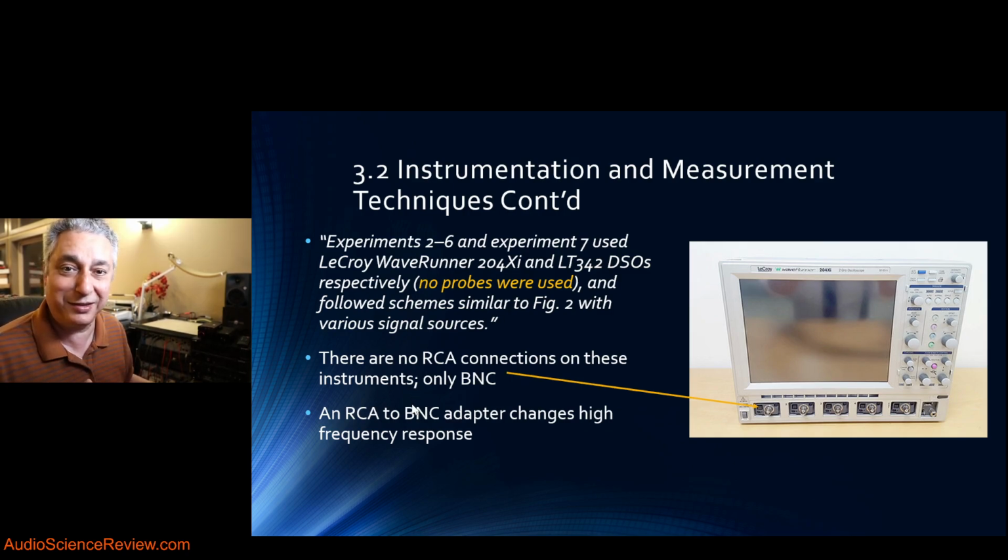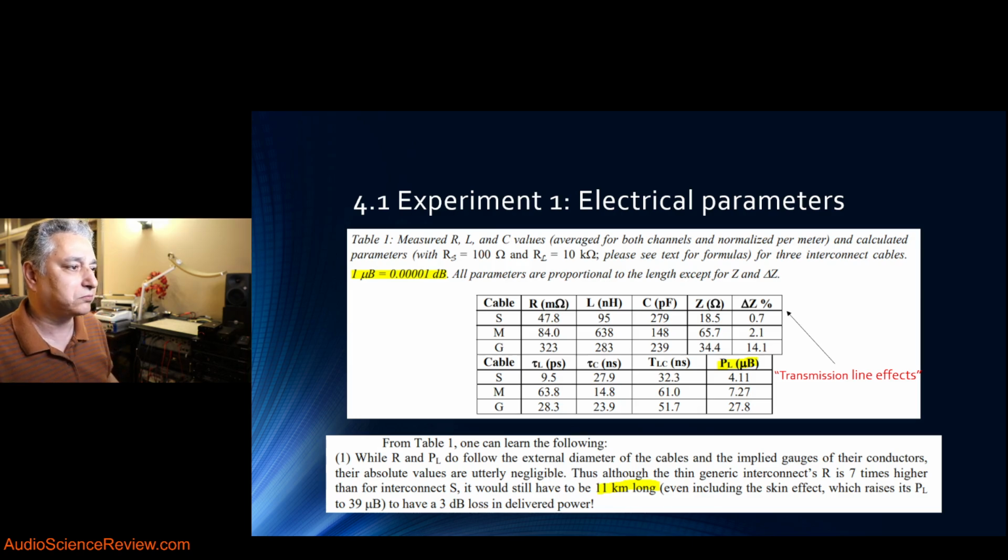The cable could be quite innocent. And so these are the red flags that I see as I read this paper, and say, whoa, here's somebody who actually doesn't know anything about what he's doing in here, because no engineer doing RF work will try to take an RCA cable and hook it up to a BNC and then hook it up again on the other end, same way, and claim to be making very high frequency measurements. So be very, very careful, this kind of testing is just not valid, and there's a lot of hand waving going on.